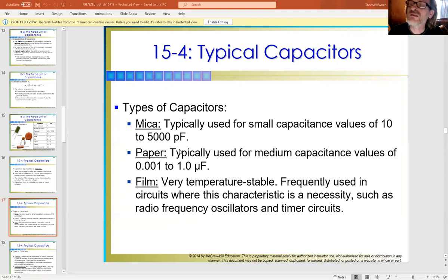We would have repair kits for these things, and what we would do, I swear to God, the first thing you would do when you get these things in is recondition them, basically replace all the electrolytic capacitors, because the paper material breaks down over time and degrades the capacitor.